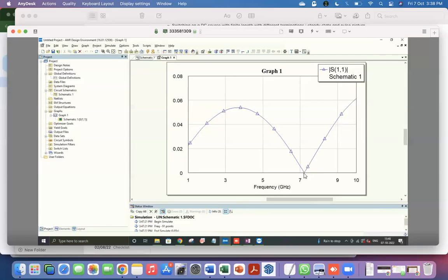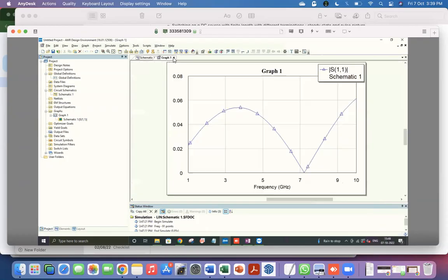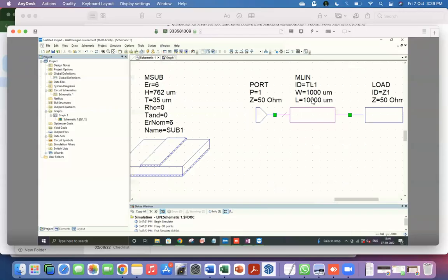Different frequencies could have different phase velocity. Well, this is supposed to be simple. Okay, it's microstrip, it's not perfect, but it's not supposed to have frequency dispersion. Let me do something which should give you a hint. I'm going to freeze this. I'm going to change the length of the transmission line. I'm doubling it. Remember that the length of the transmission line has no effect on the characteristic impedance of the transmission line, right?